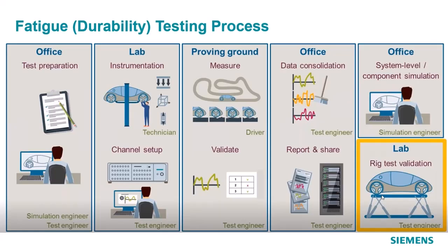Typically, when we go through this fatigue life testing, the whole process involves multiple steps. So first you have to do a test plan preparation, where you want to know where you want to measure the loads on the component and what type of loads they are going to be, whether to do instrumentation in terms of sensors that you will use, like strain gauges or load cells or accelerometers.